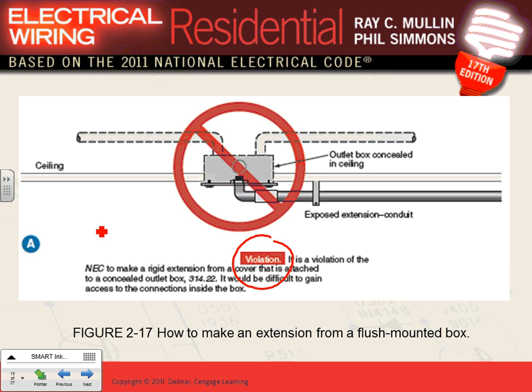What's going to happen to the termination? Very hot, cold, hot, cold. Hot, cold, what's going to happen to your termination, guys? Hot, cold. Eventually, it will loosen up. And when it loosens, it arcs. When it arcs, it creates a little bit of fire. Hopefully, it will short and the circuit breaker will trip. So most of your problems are in J boxes and device boxes if you're troubleshooting. Most of your problems. That's why the code always requires access to these devices, not because they want to bother you.